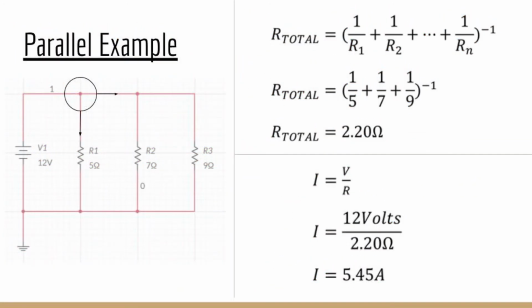Moving on to parallel circuits, as you can see in the example, there is a circle which has two arrows coming from it. This identifies that the current splits at what is known as a nodal point. The current within a parallel circuit is different to that in a series circuit and is broken up across the circuit depending on the resistance in that branch. However, the current will always sum back together before going back into the supply.